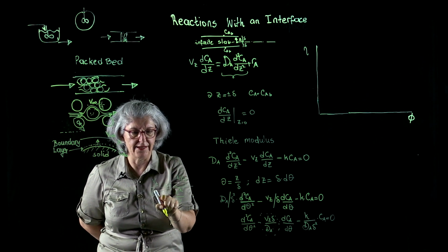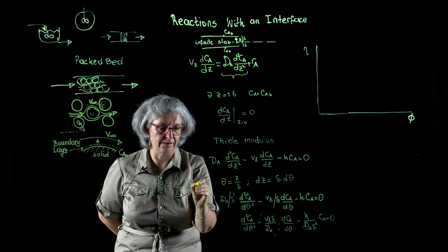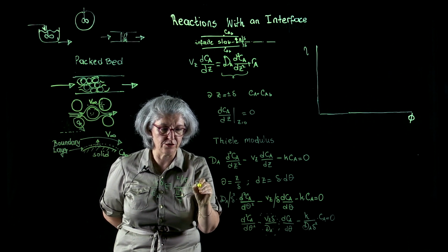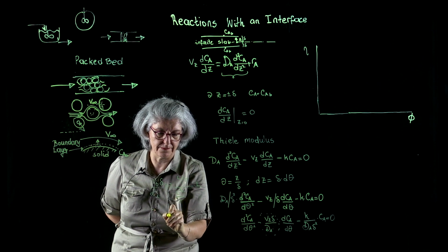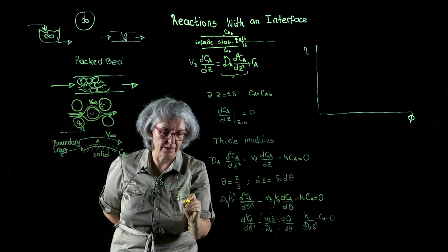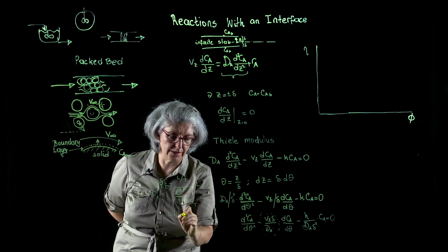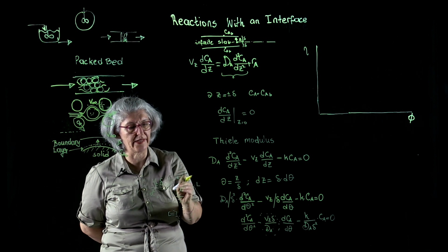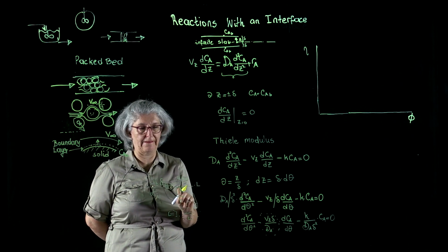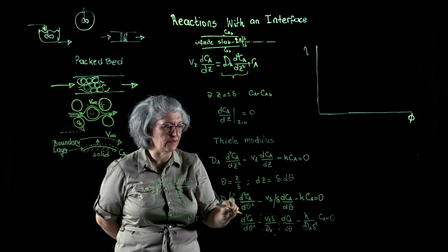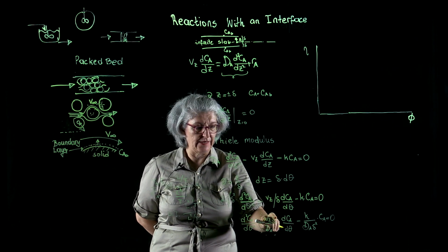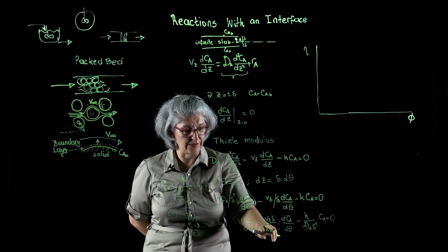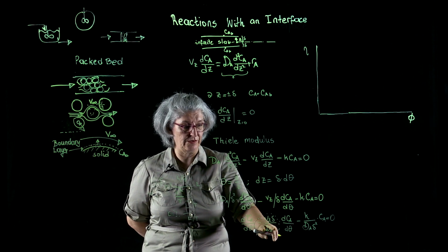So V_z delta. When we make mistakes, we just take the responsibility and correct it. Delta is here, this is length. So we have length square over time divided by length square over time. There's no dimension. Those length square over times canceled one another. All right? So here, this term is the reciprocal of the characteristic time for advection. This is the characteristic time for diffusion.